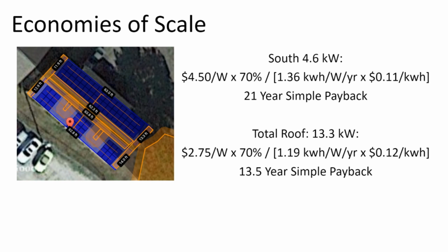As a solar installer, I want to select a couple of roof surfaces with access to sunlight. The orientation of the roof is only one consideration. In fact, in a southern climate with a shallow roof tilt, I might cover the entire rooftop if the budget and electric bill allows.